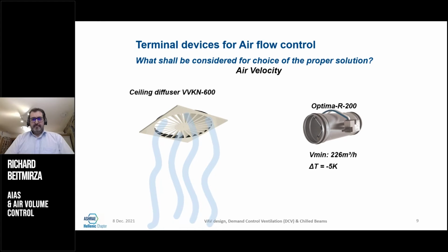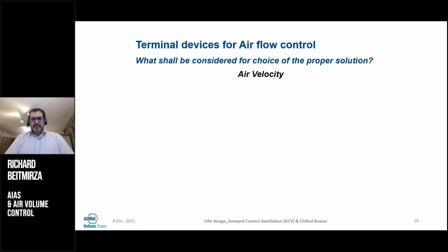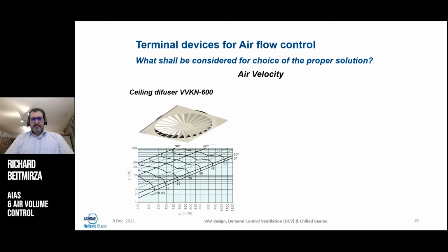Basically what we have is we have the air that is cold or cooler than the room air, doesn't have enough speed, and this will drop. This is what is called dumping. It will bring a great deal of discomfort. So we have to design all the air terminal devices in a ratio that it is able to handle.